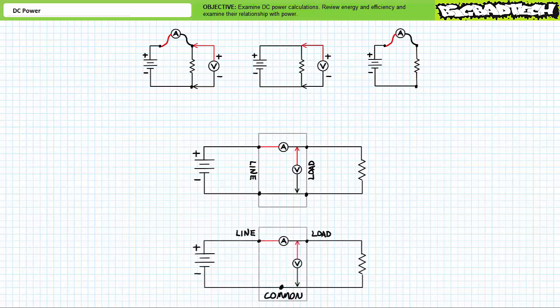Sometimes you might see 3-terminal wattmeters, where the bottom terminal serves as a common terminal to the input and output pair. Importantly, consider the placement of the meters internal to the wattmeter. Voltage is measured across something, whereas current is measured through something. The wattmeter just serves as a single bridge between our input and output if our only measurement concern is wattage.